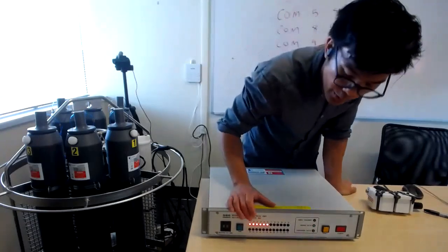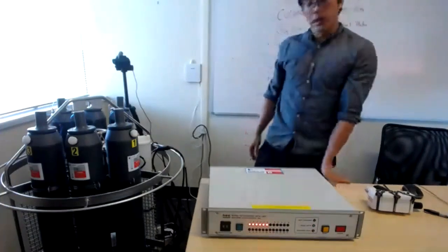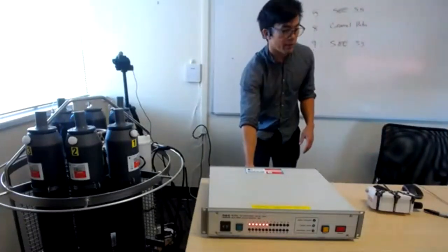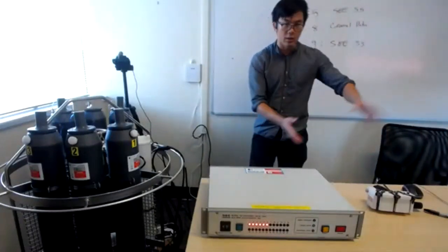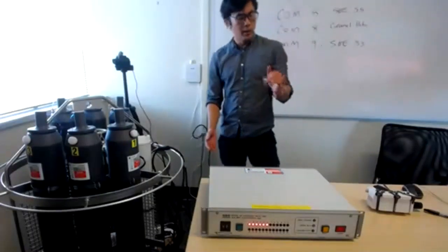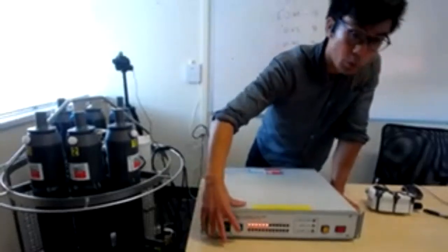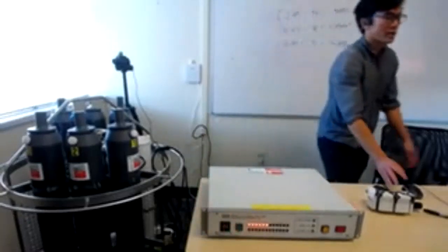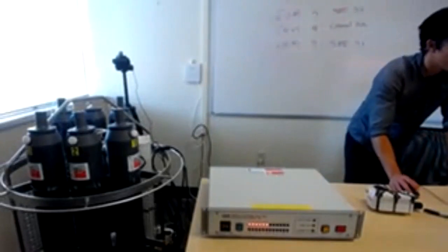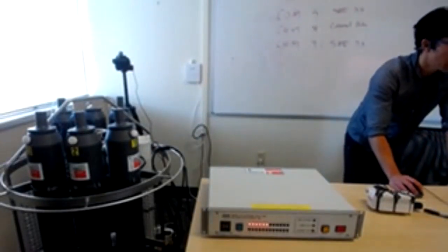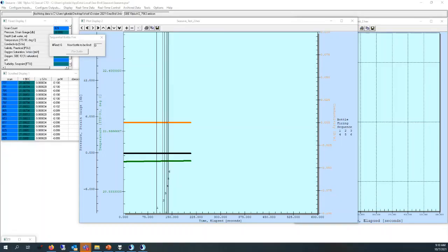So when I fired 1, 2, 3, 4, 5, 6, these bottles lit up. In the event that you don't have this carousel data serial connector connected to your computer, you can still fire bottles from the deck unit in real time with the physical button here. However, you are not going to get any bottle confirmation message in CSAVE. And so you won't see these black lines showing up, and you won't be able to get the .bl file that we're creating from this profile.